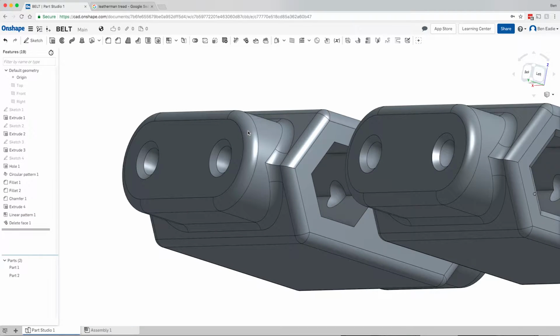The hole we have is 6.7 and we want 4.3. So let's do a little math. We need to get 6.7 and we need the hole to actually be 4.3. So 6.7 minus 4.3 gives us 2.4 millimeters that we need to offset in its entirety. We actually need to offset 1.2 millimeters on each face to give us that 2.4.